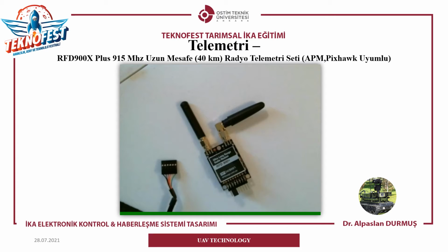You can use any antenna provided in the kit. These little quarter wave omnidirectional antennas are just the most convenient. You can use the longer half wave or even the Yagi or patch antennas on the ground station. But for sake of demonstration and convenience, I'm just using little quarter wave omnidirectional antennas.